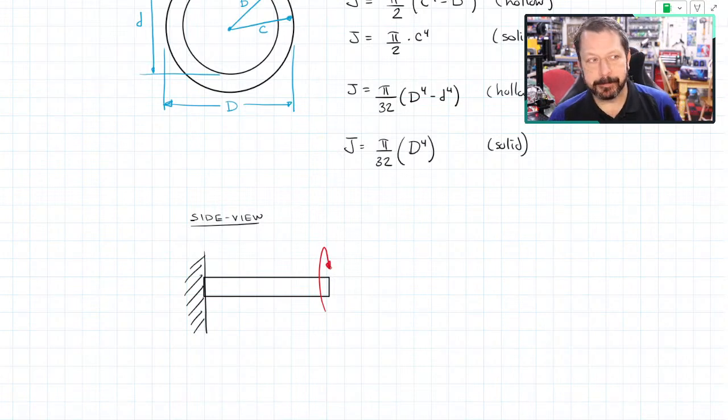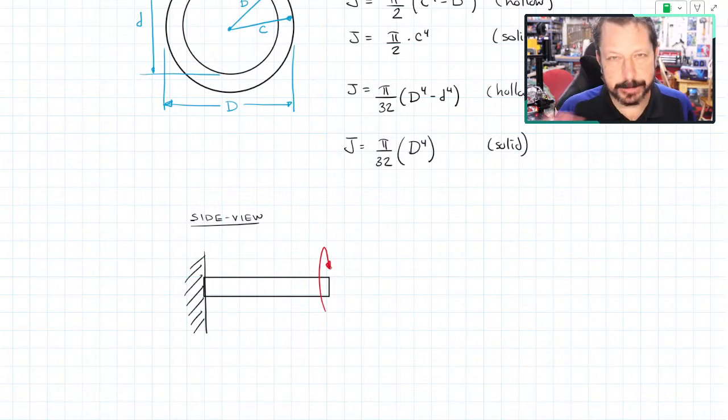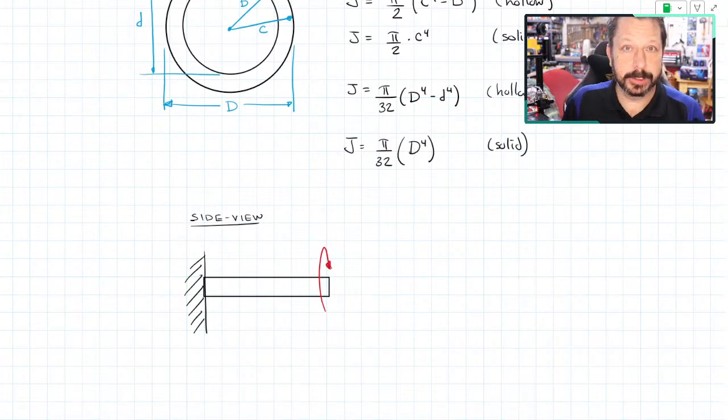Just in engineering, particularly mechanical engineering, instead of calling them all torques, we limit the torque word to whenever you've got a shaft that's spinning or twisting, and we use the moment word whenever it's something that's causing a rotation about some point, but not a shaft rotation. So we just use different words to mean the exact same thing. If you were in a physics class, it's just all torques.